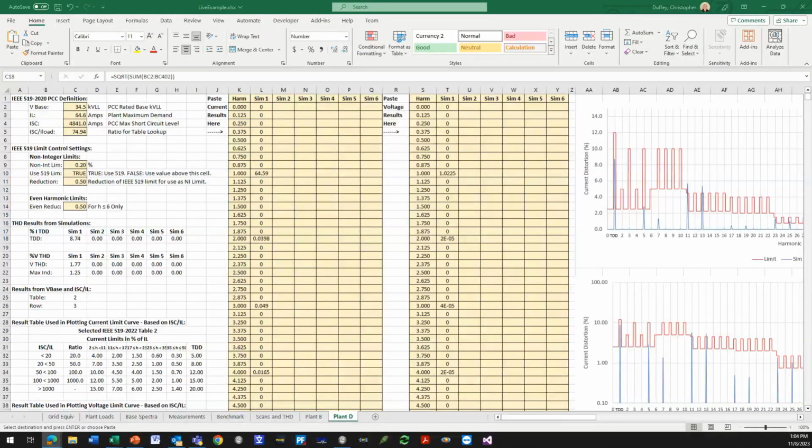So it really depends upon each situation, but yeah, I can see doing it at pretty much anywhere you want, as long as it provides the need that you have. It's within your budget. But typically, I would say most of us see medium voltage application of harmonic filters unless there's something really funky going on on the 480 and you need to keep distortion down. Let's say distortion is up over 20% or 15%. You may want to filter down low to solve the problem there rather than upstream.